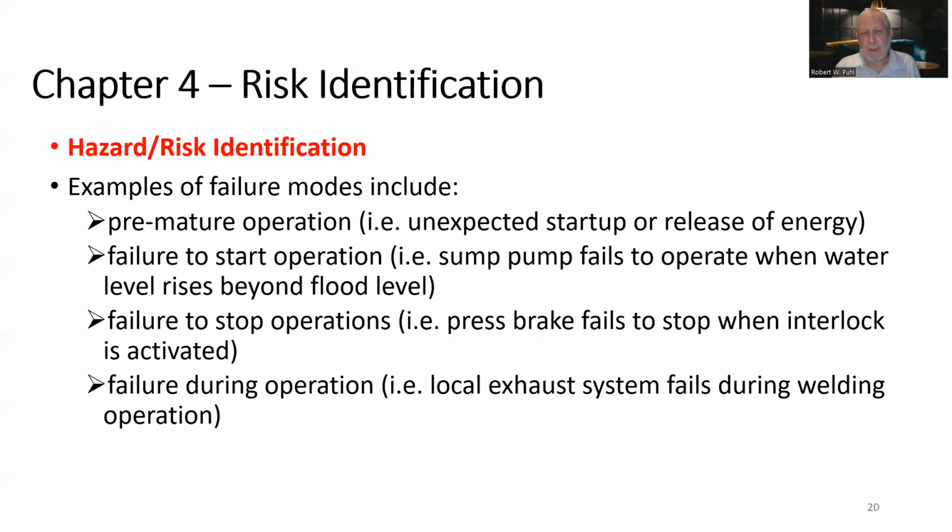Something starts: unexpected startup or release of energy. Of course, during service or maintenance, we control that with lockout. Failure to start operation: a sump pump fails to operate when the water level rises beyond flood level. Failure to stop operations: a press brake fails to stop when the interlock is activated.